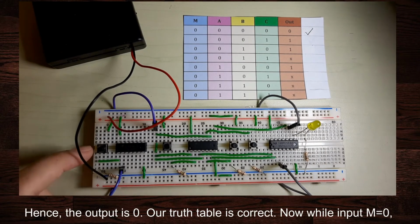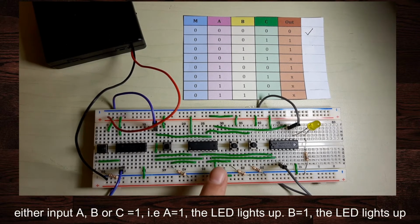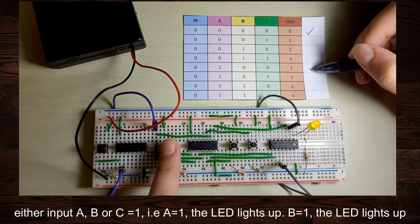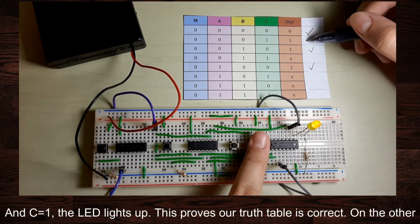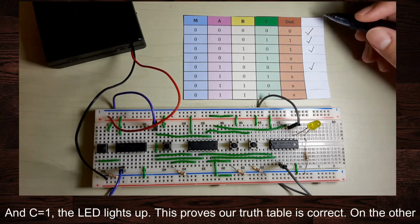Now, while input M equals 0, and either input A, B, or C equals 1: A equals 1, the LED lights up. B equals 1, the LED lights up, and C equals 1, the LED lights up. This proves our truth table is correct.